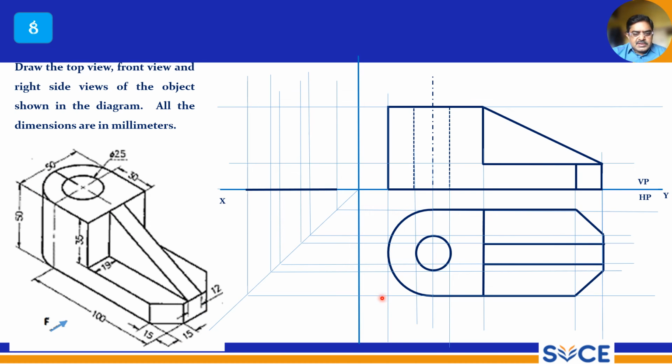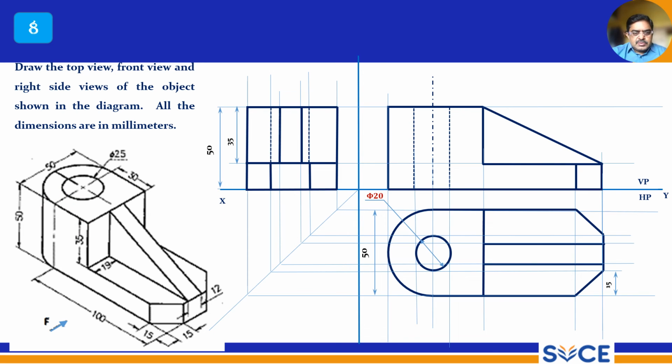So this is the width, and 15 mm. Now it will look like a rectangle. Draw the rectangle, and 15 mm you draw the straight line. These edges are visible, and those edges, and then this slant edge is visible. From here to here it is visible, and the through hole is not visible, and that should be drawn with the dotted line. Give all the dimensions carefully, and write top view, right side view and front view. This should be the front view, top view and right side view for this machine component.